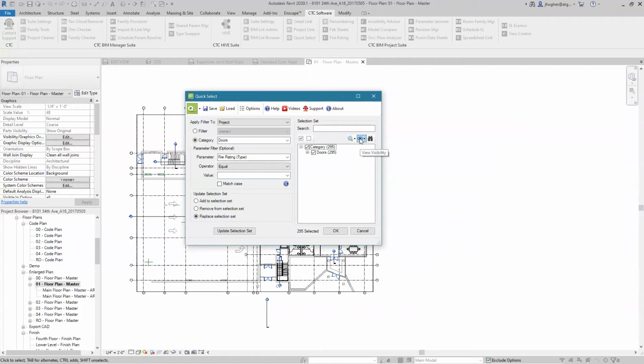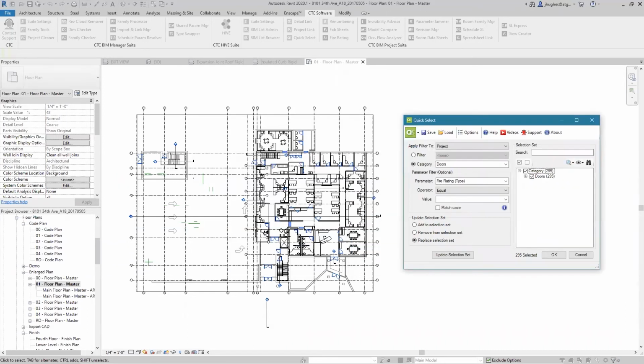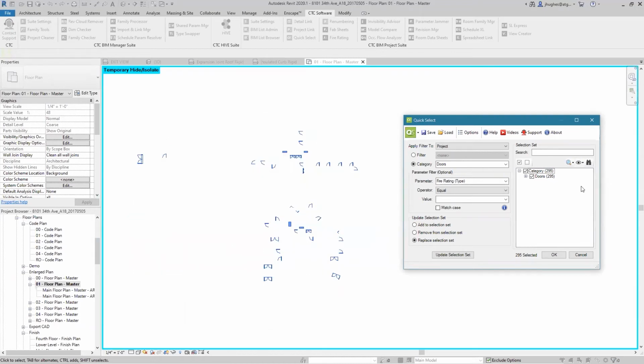You've also got some abilities over here because this one doesn't allow me to zoom and click in and do things on the side. While I can see stuff, I can't actually change the zoom in this case. But I can do things like isolate these doors and just see them. So I might choose isolate elements out of here on the right. And now I can see all of these doors, well, all doors, because they don't have any value for the fire rating.